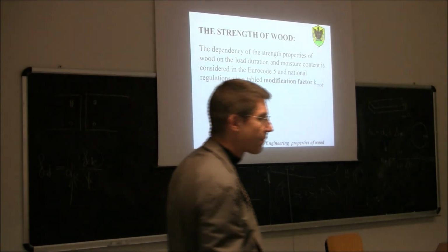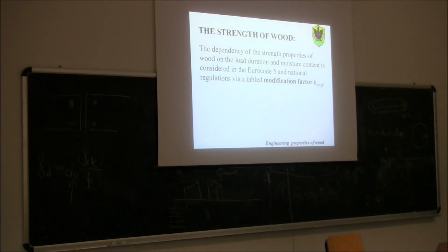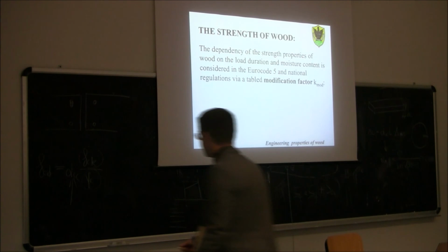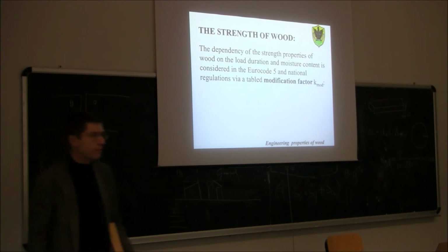The type of structural system. No, not really structural. Different for beam, slab. Yes, it would be different only for very slender slabs, would be 0.80, if I remember well. Otherwise, always 0.85, if you remember. Okay. What does this coefficient account for? Why is it never 1, always less, 0.85 or 0.80?